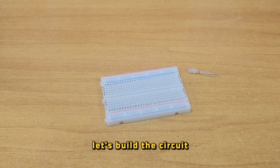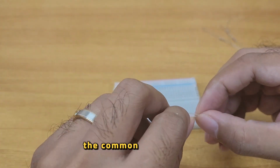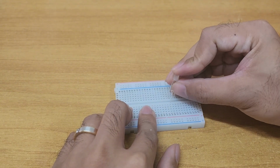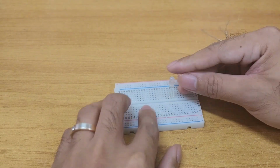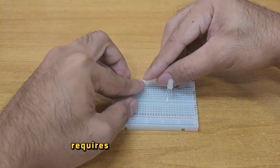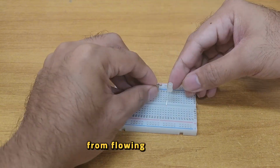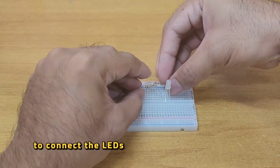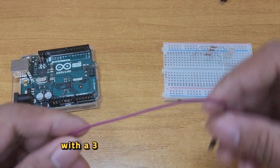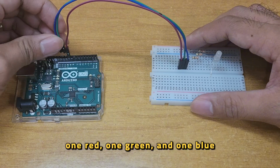Let's build the circuit. For this experiment, we will use the common cathode LED. Each LED present inside the package requires its own 220 ohm resistor to prevent excessive current from flowing through it. To connect the LEDs to the Arduino output pins, these resistors are used with the 3 positive pins of the LEDs, one red, one green, and one blue.